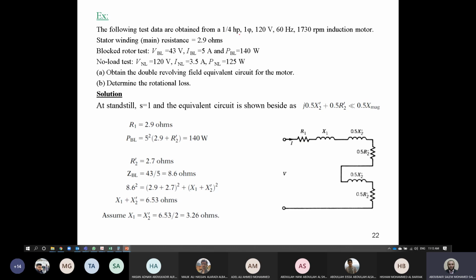So this is now the single phase induction motor rating. This is the output power now. Single phase 120 volts. So this is now considered as the input voltage. Of course it's the RMS value. Here we shouldn't say phase or line because this is single phase, guys. So here this is representing V1 RMS value. Frequency is 60 hertz. N is 1730. What is this N, guys? What is this speed here? Is it synchronous speed or rotor speed? Rotor speed, exactly. We don't have synchronous speed with this value. So this is now representing the machine rated speed of the induction motor.